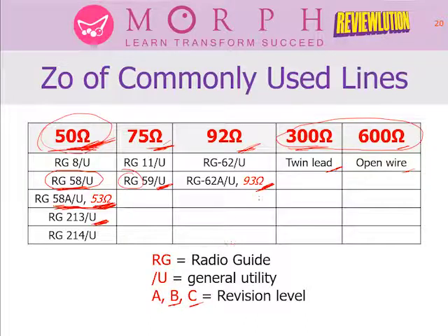So that's how you decode, no, the decoding of your coaxial cables. So again, among the coaxial cables, yung pinakamadami talaga is 50 ohms for the reason na majority sa ating mga transmitters are also rated at 50 ohms. So to connect your transmitters to your transmitting antennas, then you need to have a line that is matched talaga doon, which is 50 ohms also.